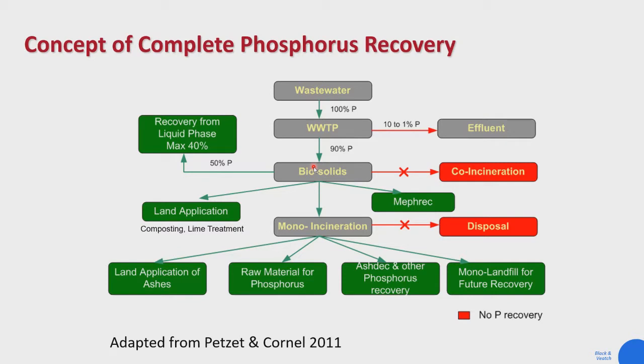If we don't extract the phosphorus, like if it's chemically bound, it just stays in our biosolids, and it ends up either incinerated or disposed. Even for land application, that phosphorus isn't necessarily available. So there's been a lot of work to ask how we recapture this phosphorus. We spent a lot of energy pushing that phosphorus into our biosolids. How do we now pull that out?